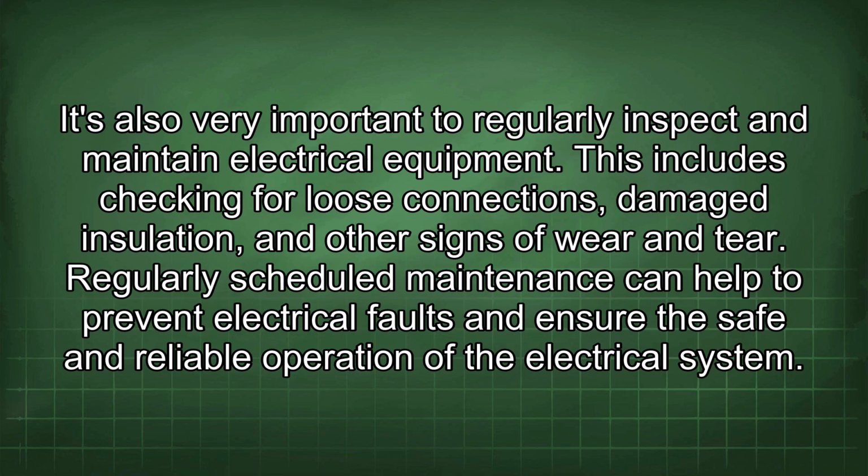It's also very important to regularly inspect and maintain electrical equipment. This includes checking for loose connections, damaged insulation, and other signs of wear and tear. Regularly scheduled maintenance can help to prevent electrical faults and ensure the safe and reliable operation of the electrical system.